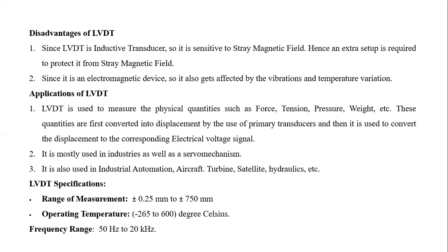Next, disadvantages. There are two disadvantages. Since LVDT is an inductive transducer, it is sensitive to stray magnetic fields. Hence, an extra setup is required to protect it from stray magnetic fields. Since it is an electromagnetic device, it gets affected by vibrations and temperature variation.